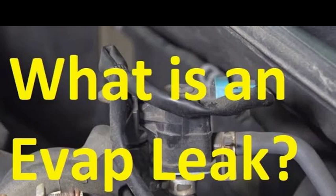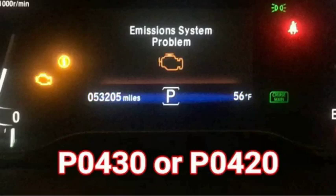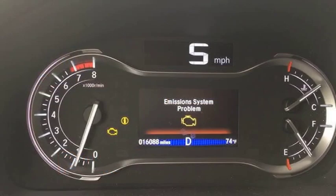Here are some additional tips for diagnosing and fixing code P0443. Check the fuel cap to make sure it is properly tightened. Inspect the EVAP system for leaks. Test the purge control valve to see if it is working properly. Check the wiring and connectors for damage. If you are not comfortable diagnosing and fixing the problem yourself, it is best to take your vehicle to a qualified mechanic.